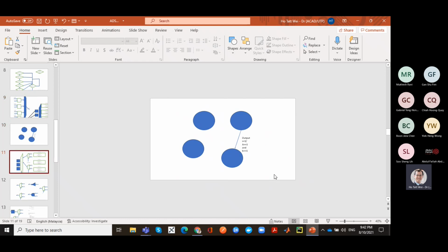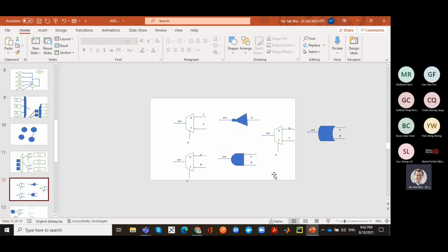That's the main point. And then I started trying to persuade you that really a multiplexer can implement any digital logic, because a multiplexer can implement an AND gate, an OR gate, and a NOT gate. And you can implement any logic with a combination of AND, OR, and NOT. Therefore, you can implement any logic with just multiplexers.